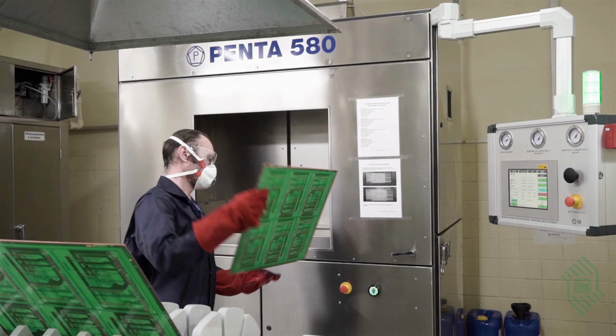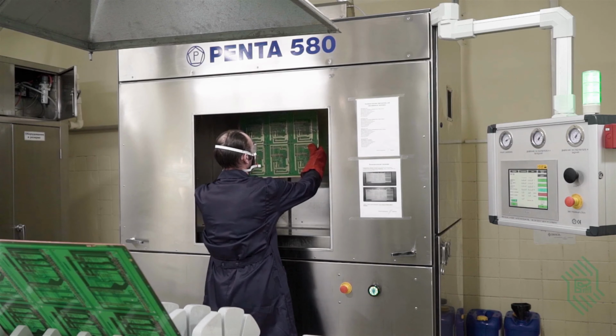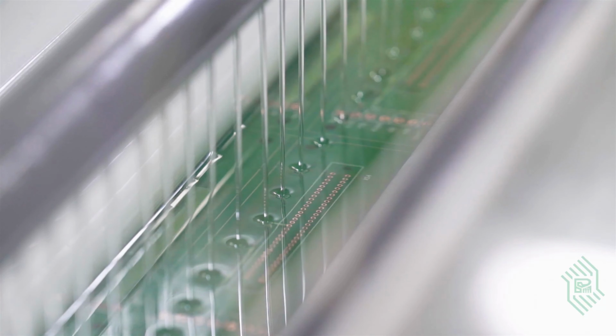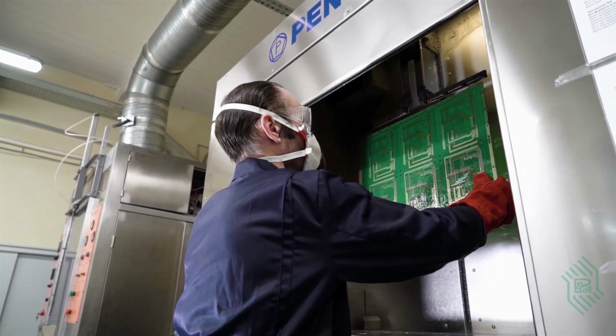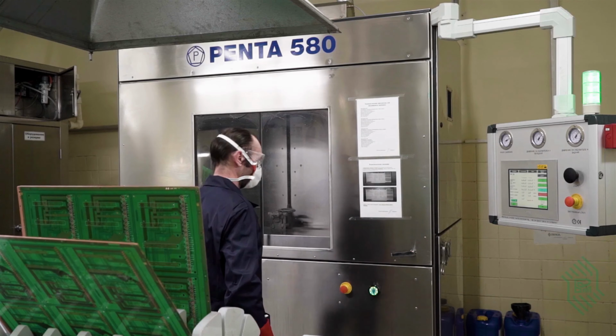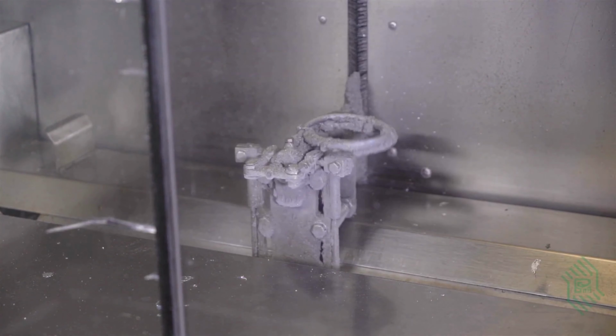For coating the pads with tin lead solder, a hot air solder leveling method is applied. The panels pass through the preparation line where they are cleaned, and then the flux is applied. The prepared panel is plunged into a bath of molten solder for a few seconds. The solder covers all the open copper sections of the panel.